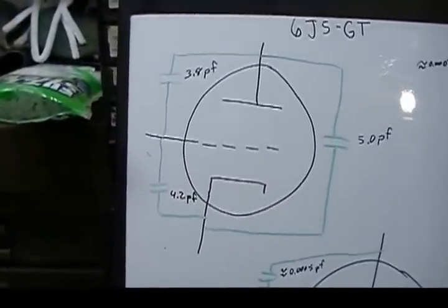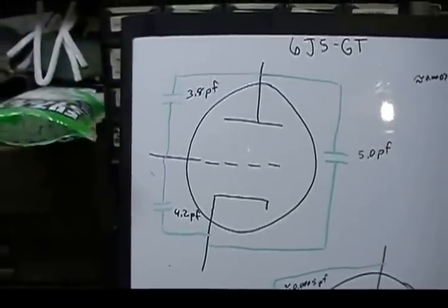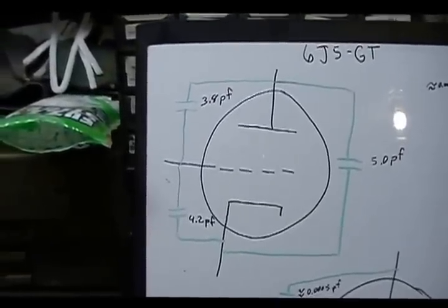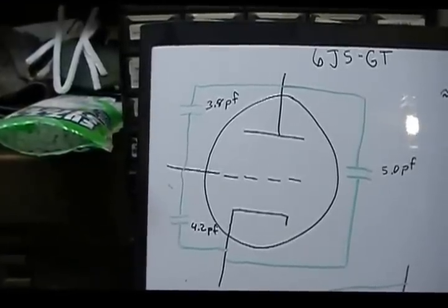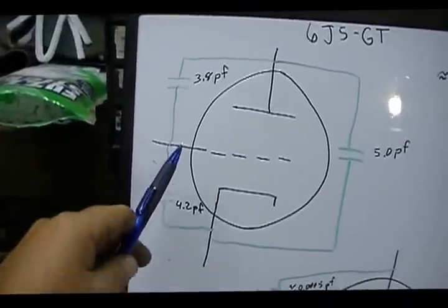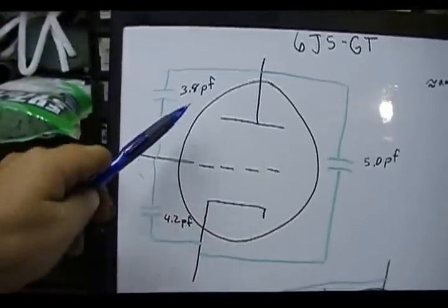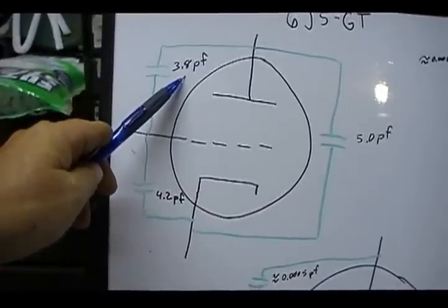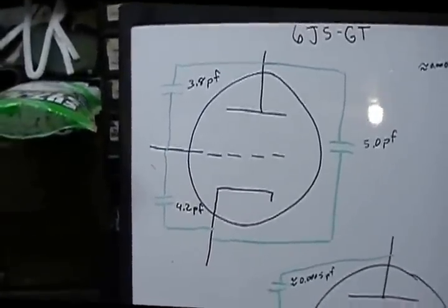It acts like a leakage in the tube. And depending on how high the frequency gets, it can even almost be like a dead short in the tube, which effectively nulls the amplification. And even at the lower frequencies, it's one of the primary reasons why the mu is lower on these tubes.